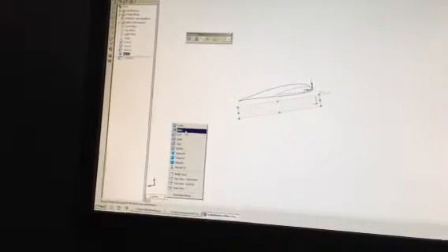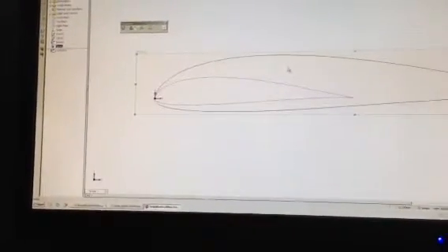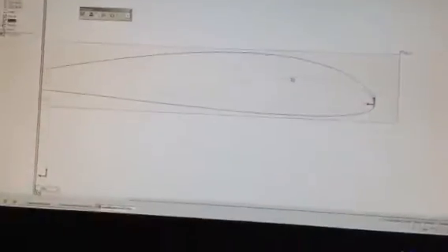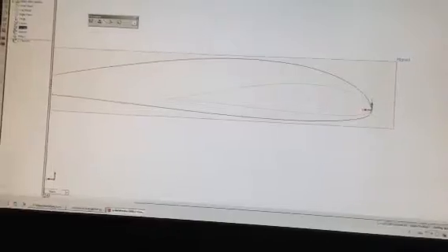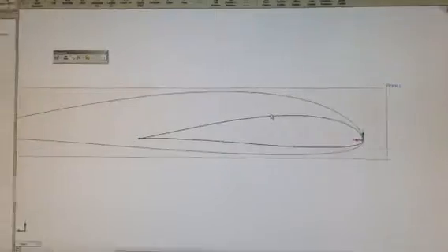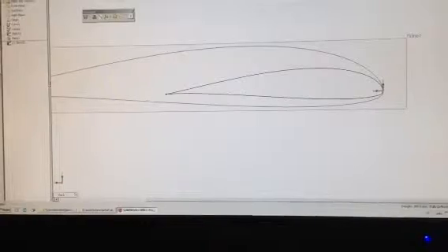Okay, so if I look on the back, the front plane is this end. It doesn't matter, let's use a front plane, and I'm going to look at the back now. That's where we're drawing. I'm going to select the smaller curve, click on it, becomes green. I'm going to convert entities, and the small curve becomes black. That means there's a sketch of the same size on it. Okay, and that's it, our sketch is done.